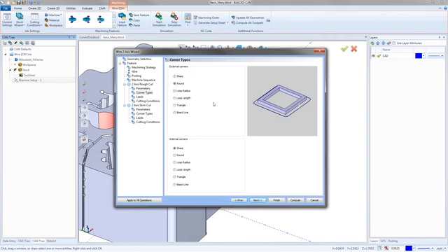Now, when you say round, this is not rounding the corners of the part. All it's doing is changing how that wire is going to interpolate and kind of roll that corner instead of doing a big 90-degree turn. You could also do loop radiuses and loop lengths, and that a lot of times will just let you keep your speed up in those corners and come back through. You could do that on external corners as well as internal corners.